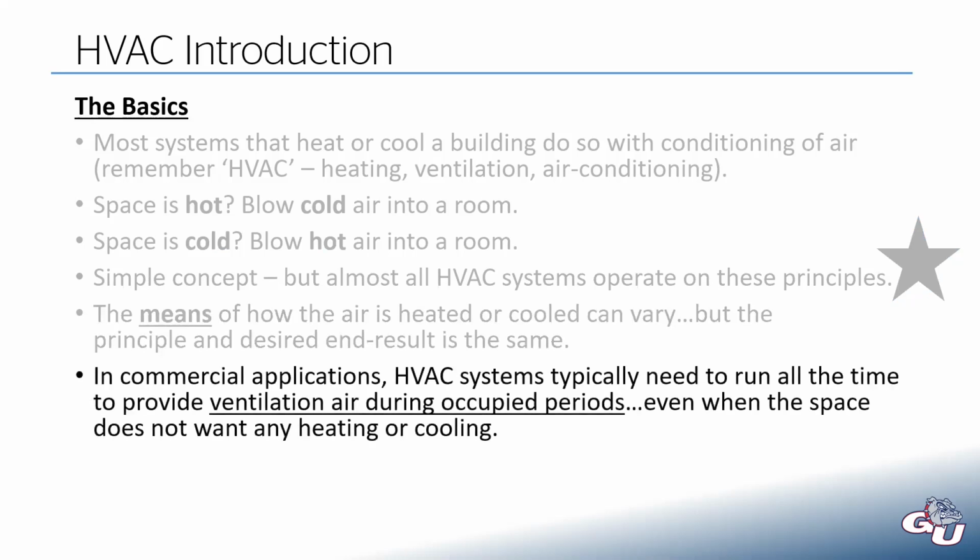In commercial applications, we talked about ventilation on day one in this class a bit. In commercial applications, meaning any non-residential, you typically have to run these systems all of the time to provide that ventilation air during those occupied periods. So even when the thermostat on the wall says, hey, I'm perfectly happy right here, I don't need heating, I don't need any cooling, we still have to run that system to provide ventilation air. And that's a code requirement.